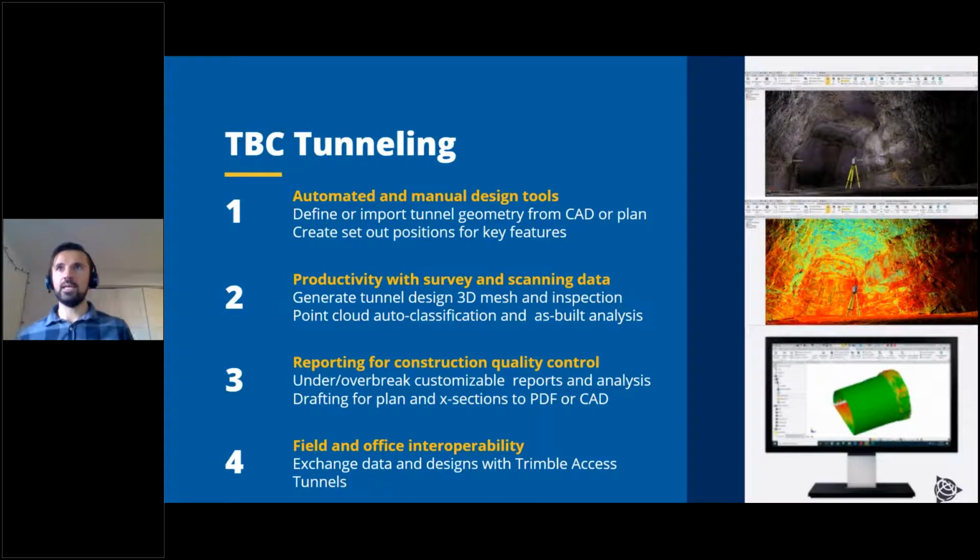Once you've collected that data, there's a variety of tools to clean it, process it, and generate visuals from it, whether it's a 3D mesh, whether it's a report, or an as-built analysis. And once again, all of that is cleaning all of the noise from the scan data and making sure that what you're getting is the data that you want. Of course, reports, a variety of reports. Jeff and I are going to demo some of those to you today, especially as-built reports, which are very important in tunneling, but as well as other types of reports like the inspection workflow, especially for NATM tunnels, drill and blast tunnels, where we've got this iterative process of tunnel construction.